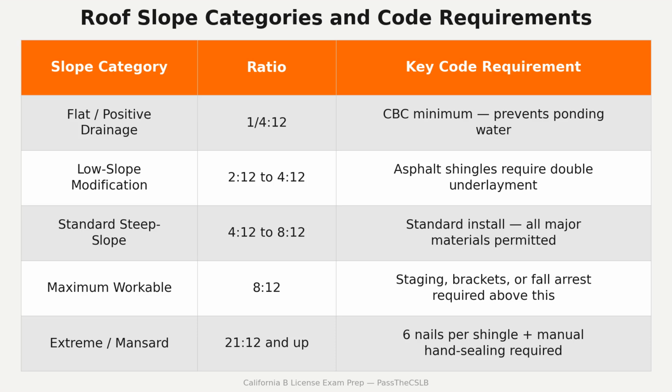When two wings of a building intersect at right angles, two junction types form. At exterior corners where sloped planes face outward, a hip. At interior corners where sloped planes face inward, a valley. Valleys concentrate the drainage from two converging roof planes. They are the single most vulnerable water intrusion point in any roofing assembly. That principle is going to come back when I cover flashing.